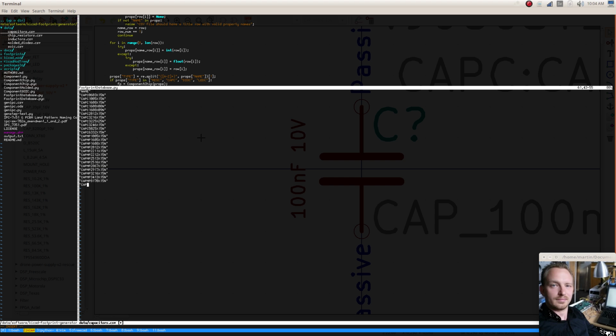So if I want to add a new capacitor of whatever size, I can do it very simply using this wizard. Say there was a capacitor 4.5 millimeters by 6.5 millimeters with a height of 3 millimeters and board density normal, it would just be a matter of adding a simple line to this file.